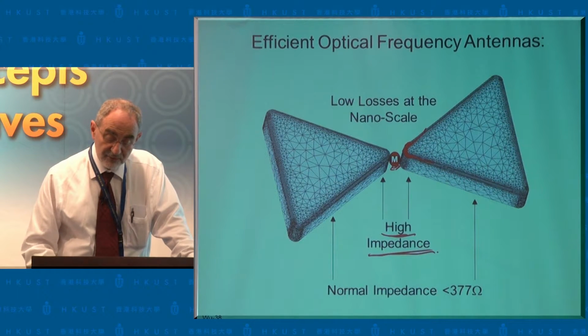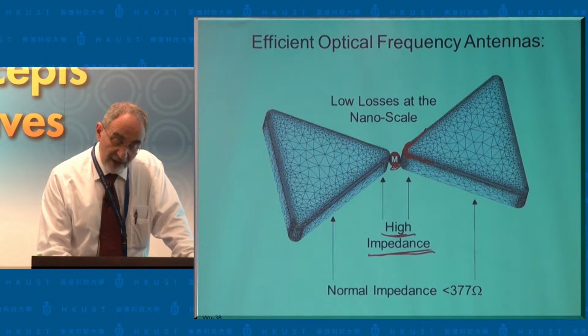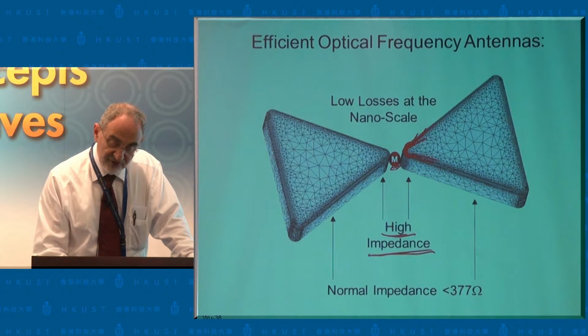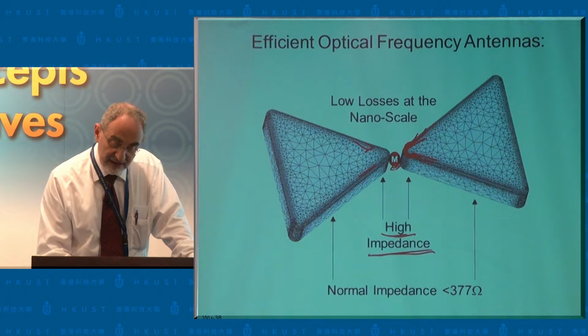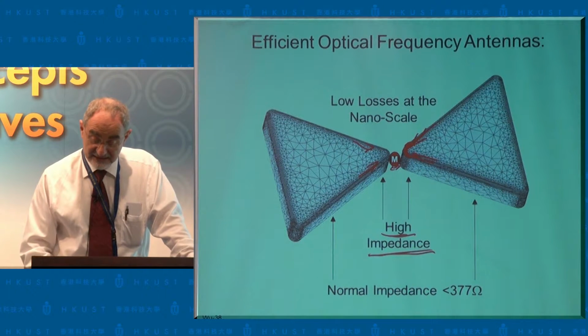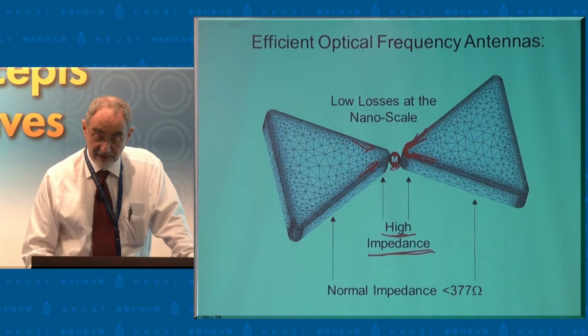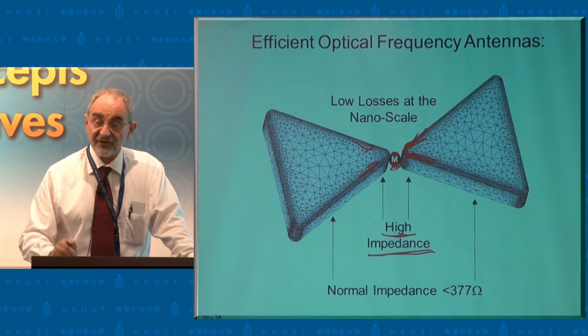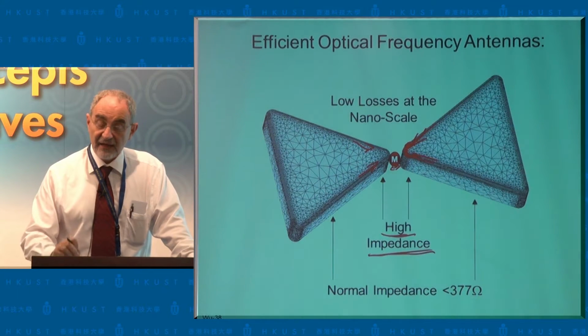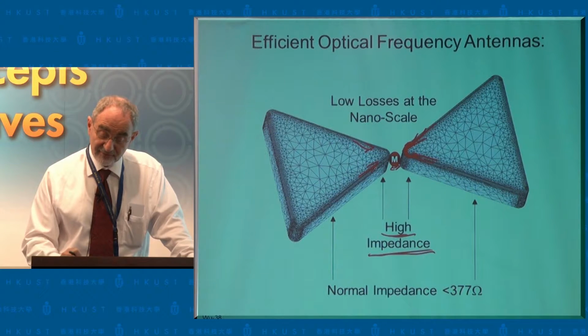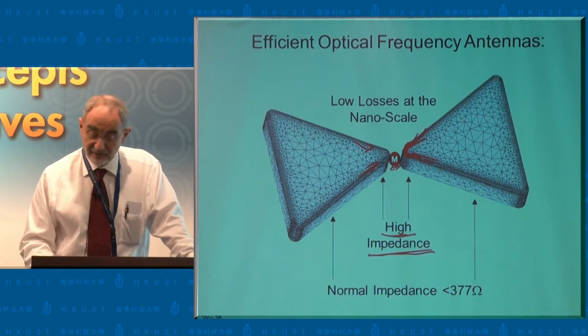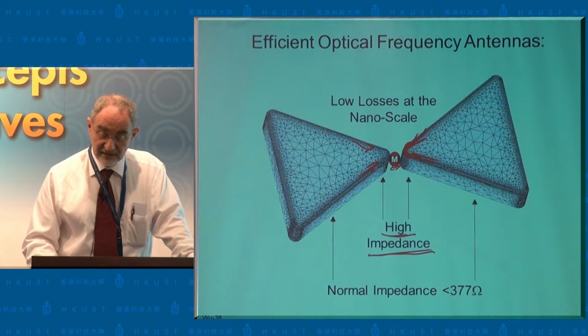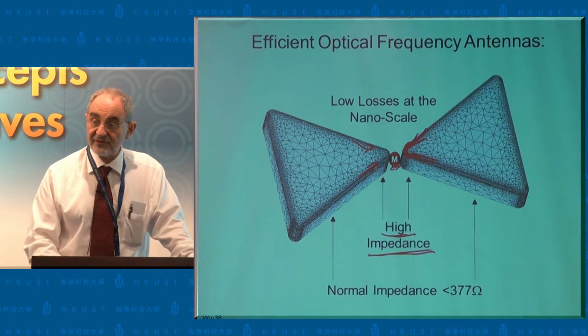And so this is what we're struggling with: what is the actual expected resistance when we have this tremendous concentration of current, of course, on both sides. We don't have very good numbers for that. I can make estimates, but it's ultimately going to tell me how fast I can make the spontaneous emission. We're up to 35 times enhancement. If I can get 200 times enhancement, I beat the fastest laser. Can I even get to 2,000 times enhancement? Everything hinges on this series resistance.